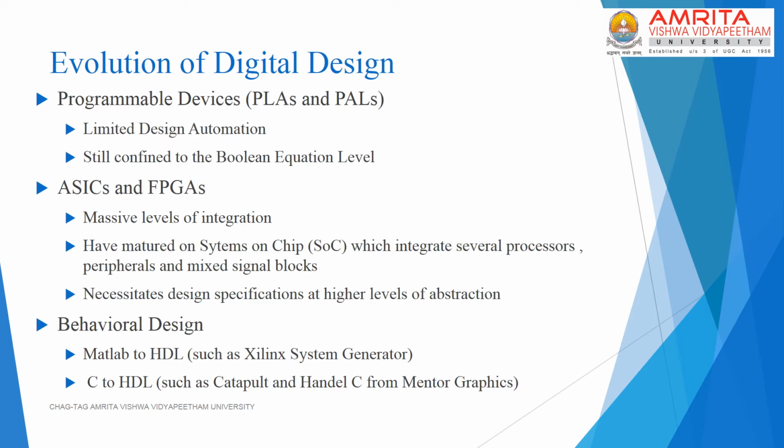Some limited effort towards handling the complexity of glue logic was made in the development of programmable devices like PLAs and PALs. These were essentially arrays of AND and OR gates, and they were able to reduce the component count in microprocessor based systems to some extent.